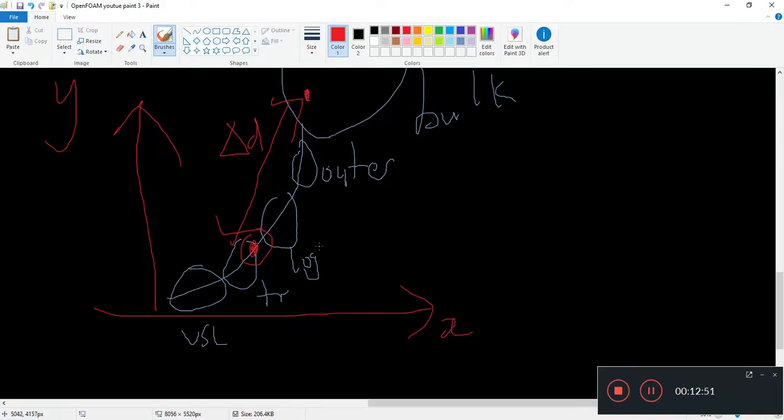So there are many trip points along the xy axis, so to speak, because when you join these points, it will basically tell you, okay, here's laminar, and here, laminar plus transition, and here's the fully turbulent region.